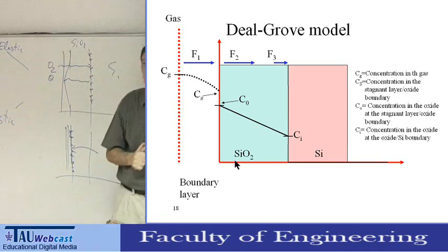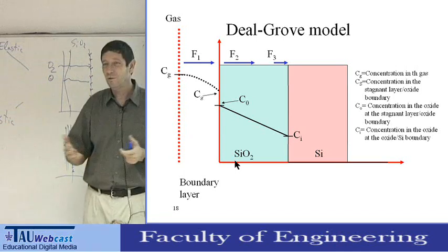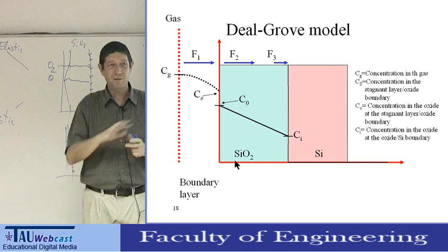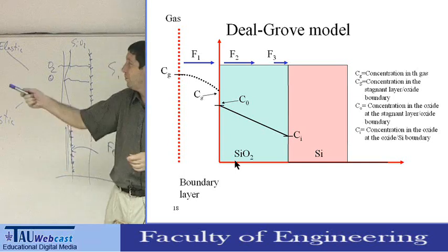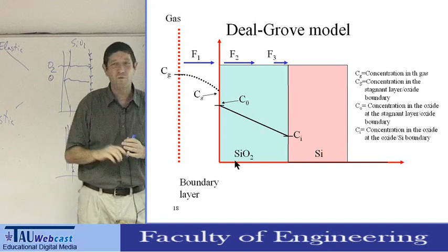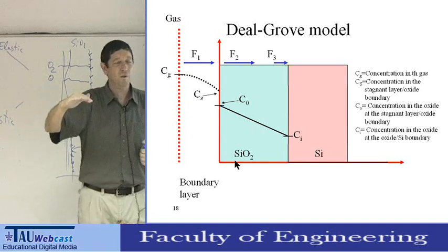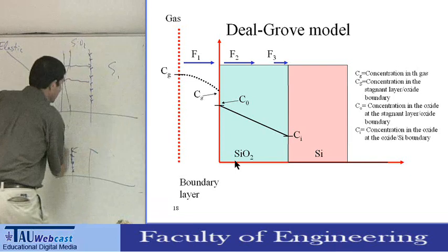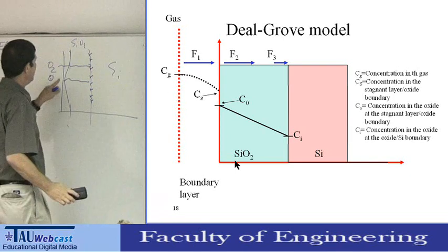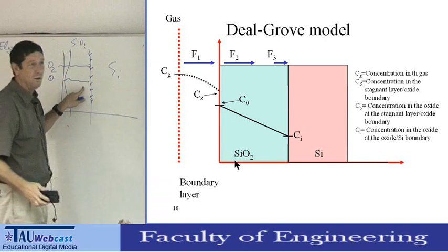You all know that when you oxidize iron, you generate rust, and the rust is not so uniform. Aluminum, for example, makes a very nice oxide on top of it, and the oxidation of aluminum stops because the diffusivity of the oxygen through the oxide is very, very slow.